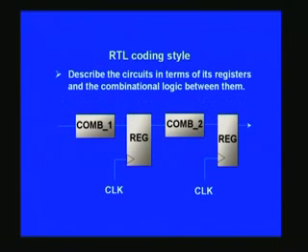And basically, the RTL coding style is once again the same as synchronous design as such. You have a combinational circuit, and it can be any complex combinational circuit, and then follow this with a register, registering this combinational output as such, and this may be an intermediate output as such, and then follow the same pattern successively, and this keeps going in this fashion, and data flows in this fashion naturally. It is normally referred to as a pipeline, which we will cover in depth later on when we deal with arithmetic circuits as such. And for the time being, this is enough if you know that the RTL coding style is basically based on separating out combinational as well as sequential circuits as such.